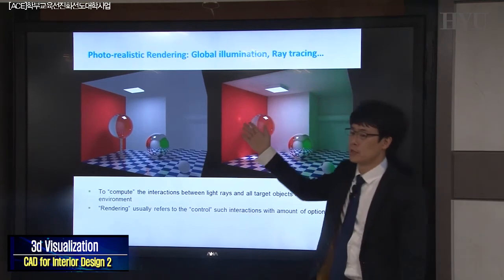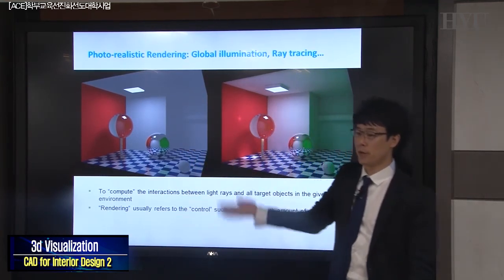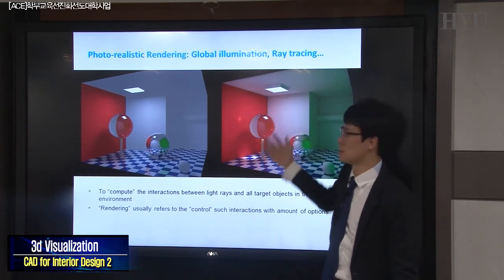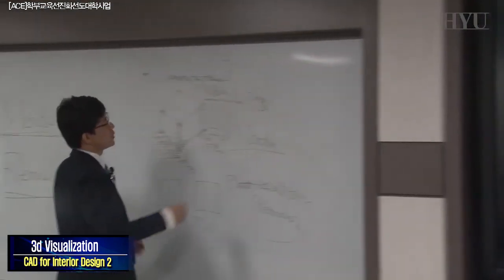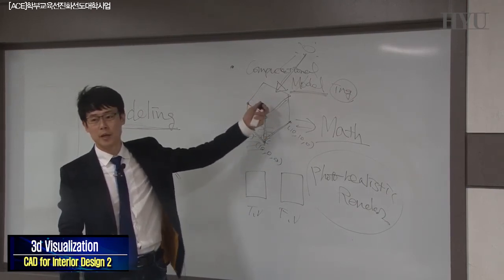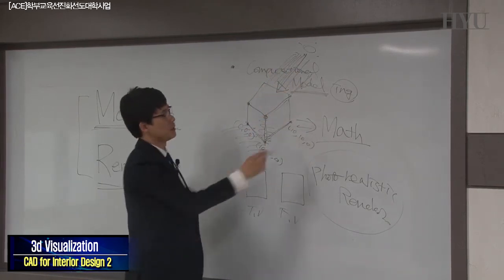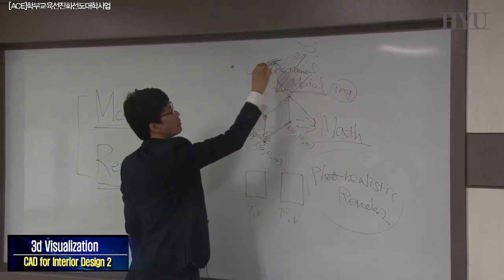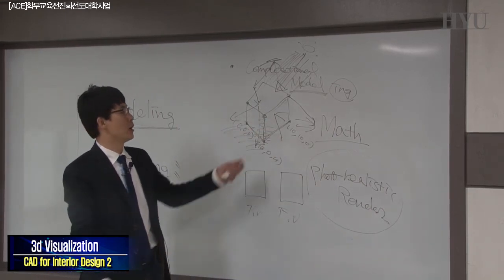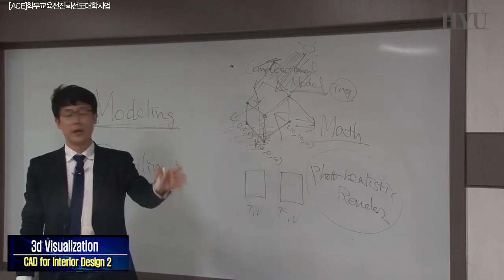You may see GI. Turn on GI, turn off GI. It makes your computer much faster or slower. If you turn on GI, it's very slow, because it has to trace all the rays. What are rays? Here is the lighting source. We usually draw an arrow for representing a sun ray, but actually it's not one single line. Millions of rays, and one by one should be calculated. Reflected, reflected, and this one reflected, again reflected to here, to there, and so on. You cannot anticipate how it works.